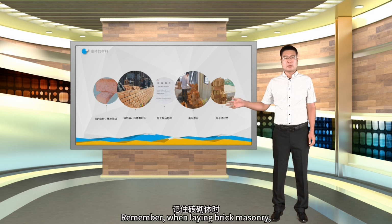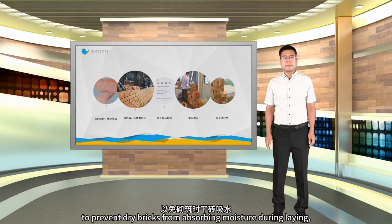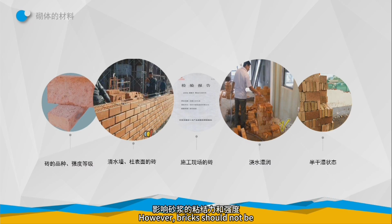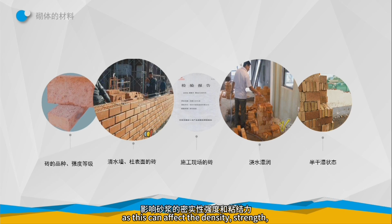Remember, when laying brick masonry, except in winter, bricks should be watered 1 to 2 days in advance to prevent dry bricks from absorbing moisture during laying, which would reduce mortar workability and flow, and weaken its bonding and overall strength. However, bricks should not be overwatered to the point where they cannot absorb excess moisture from the mortar, as this can affect the density, strength, and bonding of the mortar. Overwatering can also cause mortar to fall off and bricks to slip.